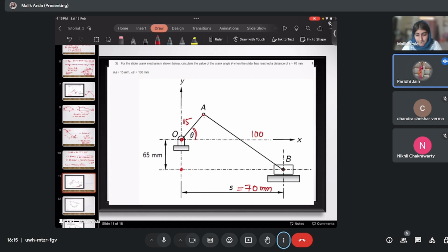Here it's given A is equal to E, the offset. B we are taking as S, and C as L2 square plus S square plus E square minus L3 square by 2 L2. Yeah, that is correct. Then theta is 2 tan inverse of A plus minus root over A square plus B square minus C square by B plus C. Yeah, you're using the correct formula, but then why are you getting the wrong answer?